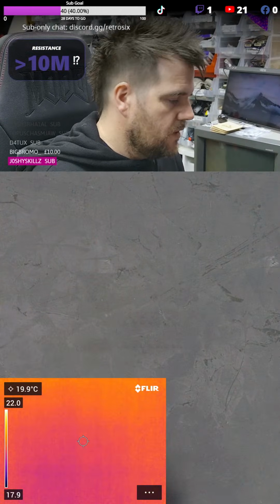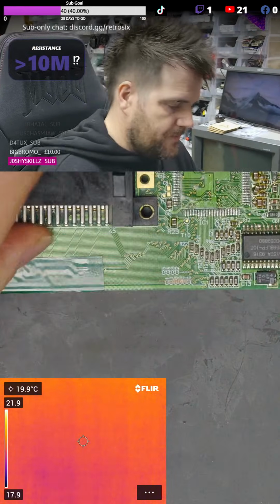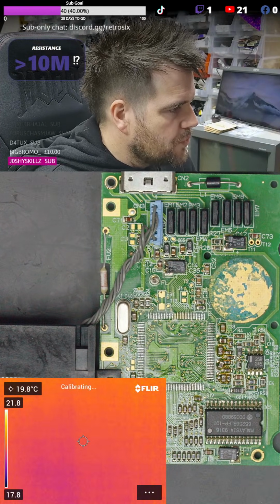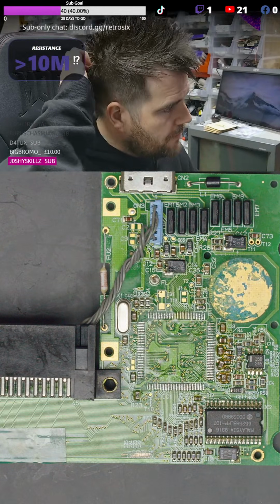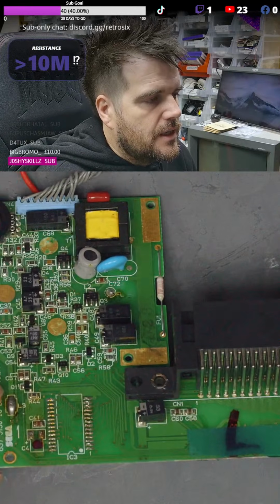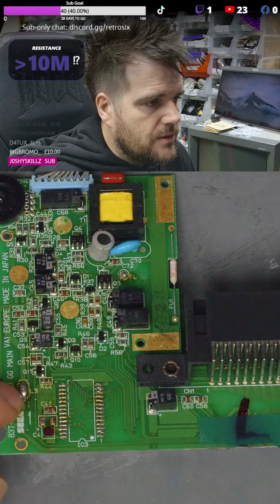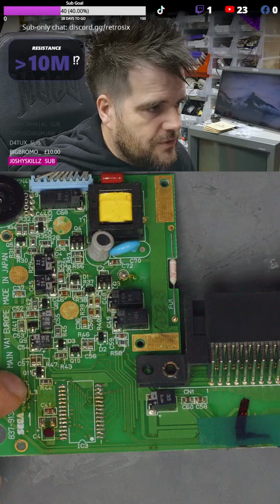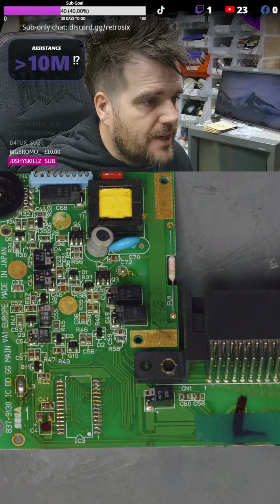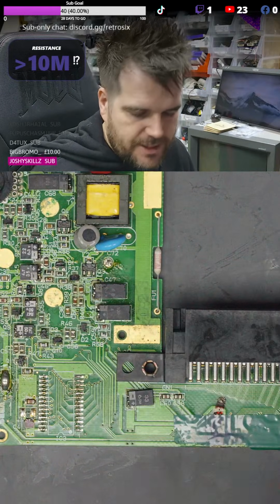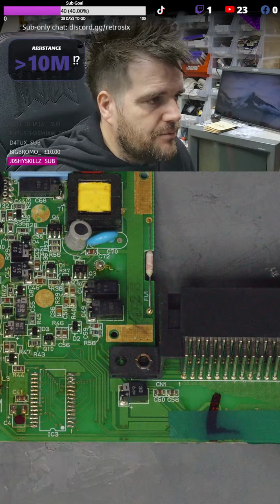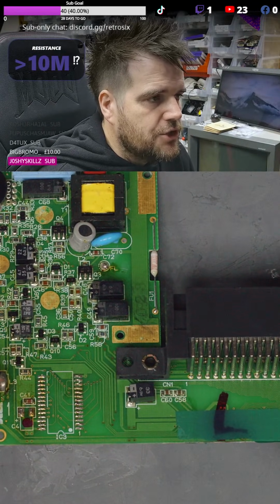Watch out for reflections, basically. So I don't think there's much more to cover in terms of detecting shorts. The only thing is, inductors are the thing to look out for. If they get hot, it's not going to be the inductor, it's going to be something else. So remove your inductor and inject 1 volt either side, or even 0.5 volts is your safe bet, because GPUs and things can actually run at 0.5 volts. So injecting like half a volt is safe on pretty much everything anywhere to find a short.